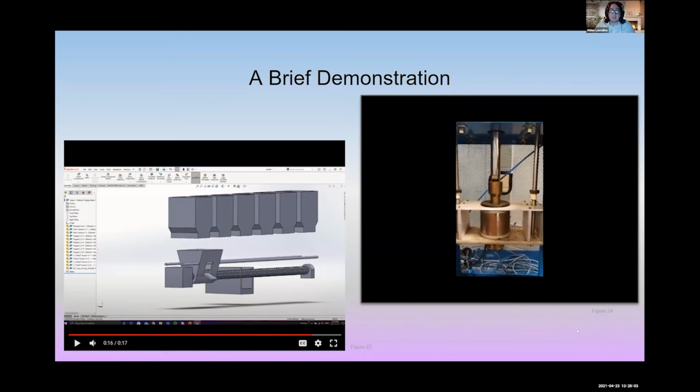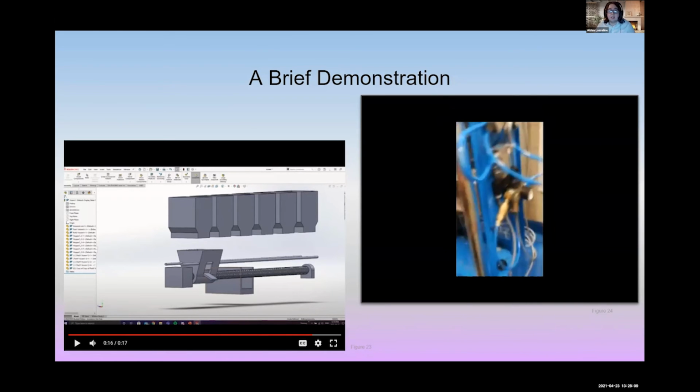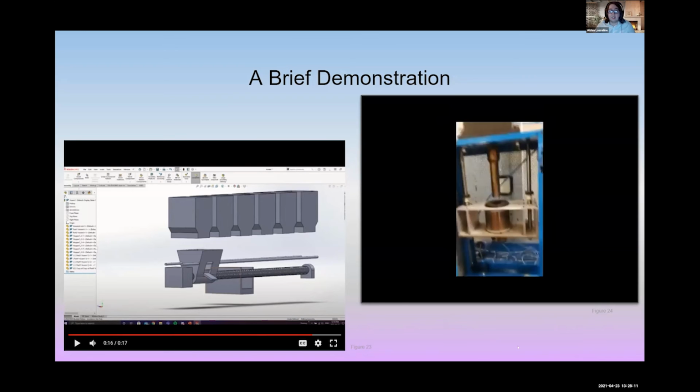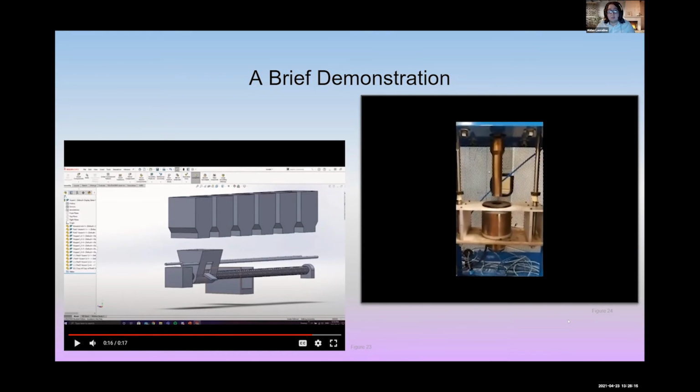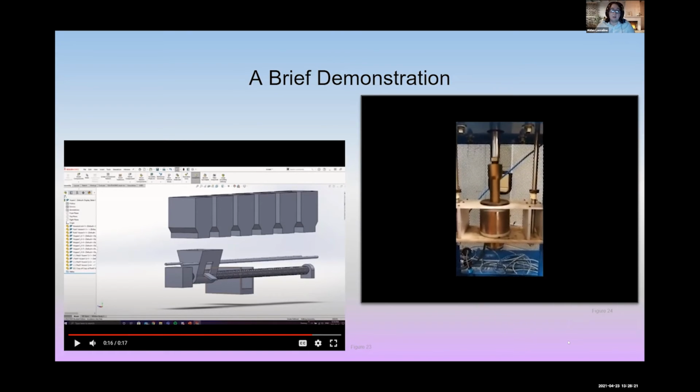Then the PLC waits a few seconds and closes the safety valve and stops air from filling the cap area, while allowing air to flow into the annulus area, causing the piston to raise back up. The safety needs to be opened before lowering the piston because as a safety feature, we do not want any chance of the piston dropping while an operator has their hands in the machine.